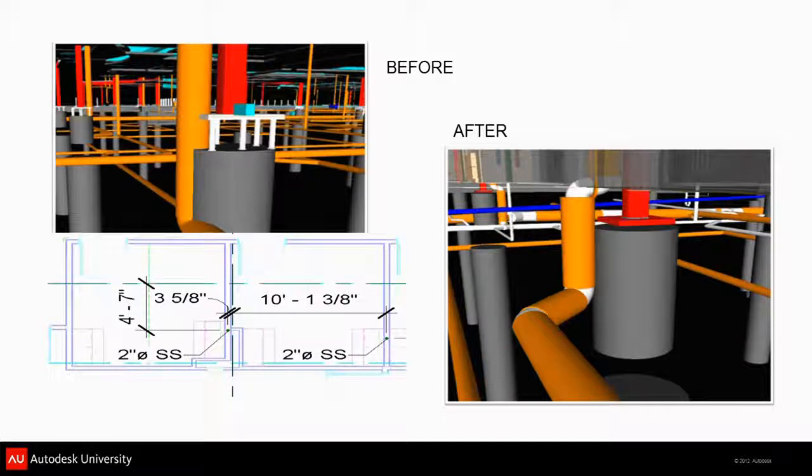This is a roof drain riser. The plumbing model originally had there, the structural engineer didn't have the base plates modeled. Now, could the plumbing modeler have known that there's structure there? Yes, he probably should have. But it wasn't modeled. When the fabrication model came in, it's clear something had to give. And so when it looked at moving that roof drain out to miss the structure, then you had to move the fur outs. And so these are common areas.